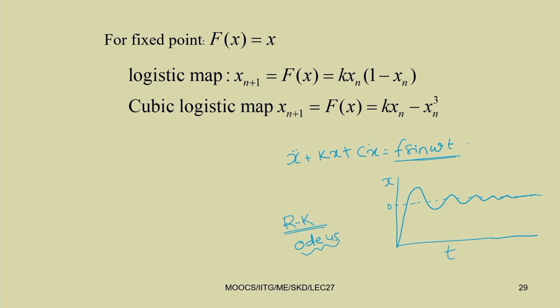Differential equation solutions. In case of forced vibration also, you have a force, for example let omega equal to 2 and omega n, which is root over k by m, equal to 1. In that case the system will have two frequencies of oscillation.